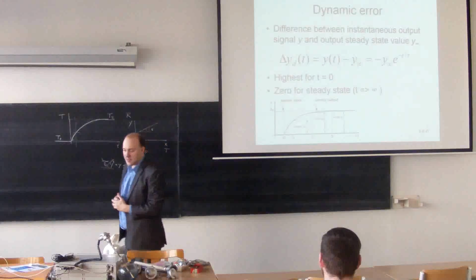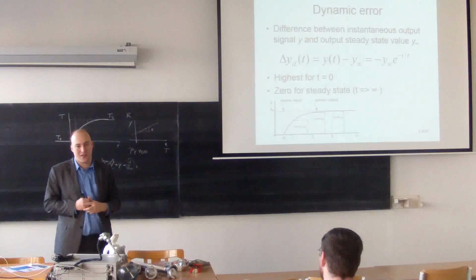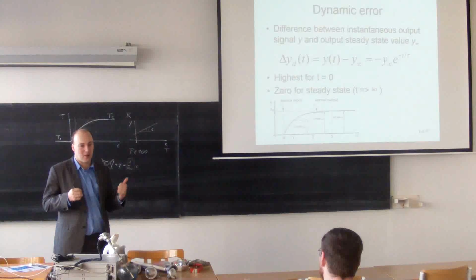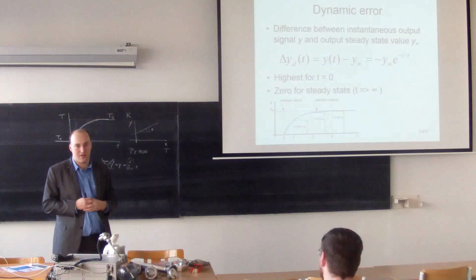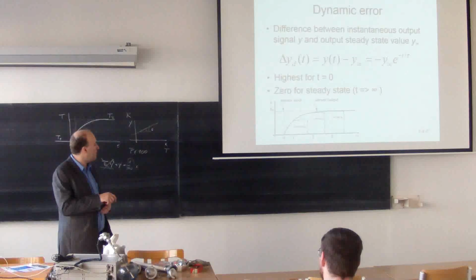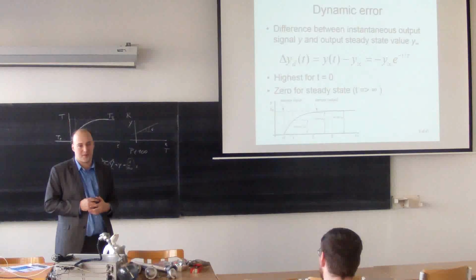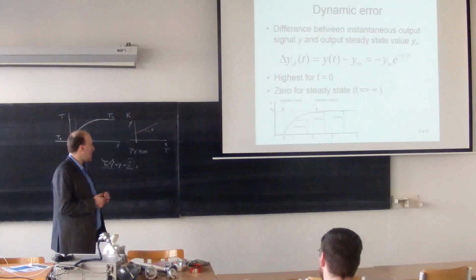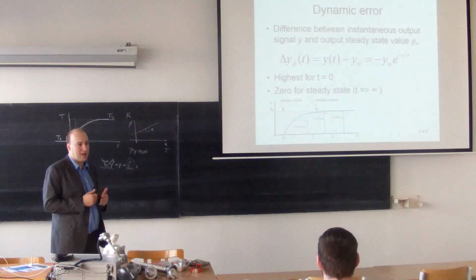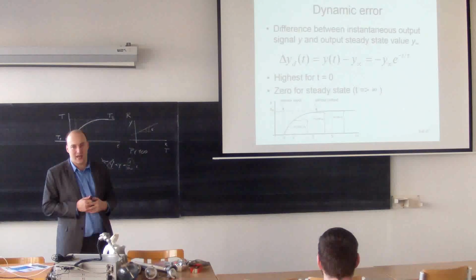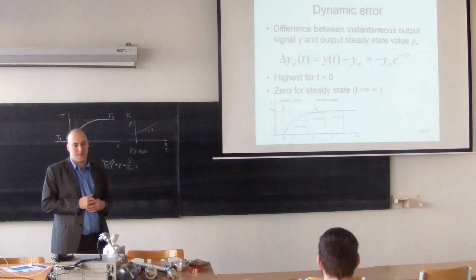So it means that, for example, if my sensor has a time constant of 1 minute and I want to be within 99% of the new steady state value, I will have to wait about 5 time constants, so 5 minutes. If I am satisfied with lower precision, within 95% of the new steady state value, I can wait only 3 time constants.